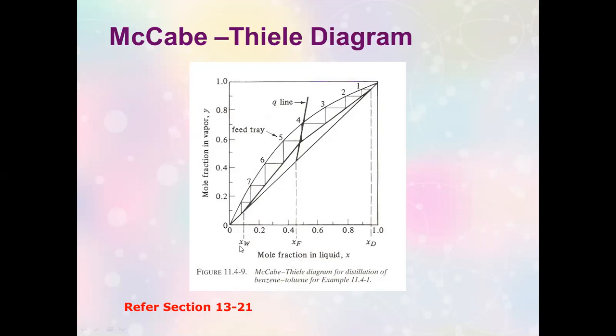graphical technique, because in the second part of this set of slides on part 2 of distillation, I'll be discussing the analytical steps. So it's 7.8, but the last step is the reboiler. So the theoretical number of stages for your column is only 6.8. So we subtract 1 from the number of steps that we have made here. So 7.8 minus 1, that would be 6.8. That would be our theoretical number of stages.